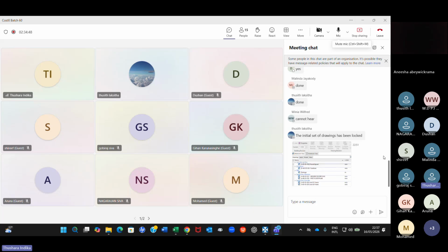Or you will see a drawing, and in the drawing you have to drag the lines to the appropriate position to reflect the revision. Once you have done this, you have to accept all the dimensions. Then you will see all the quantities back to the original quantities, plus the revised drawing will appear here.